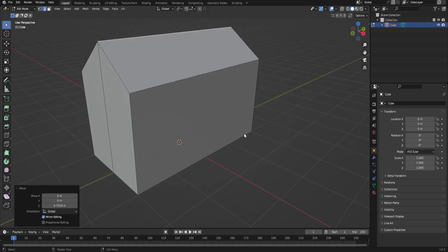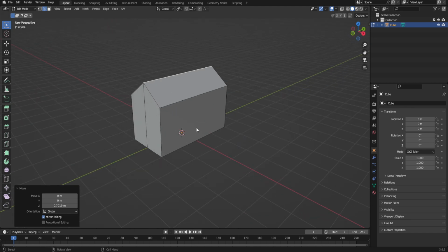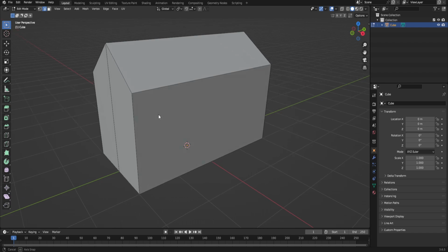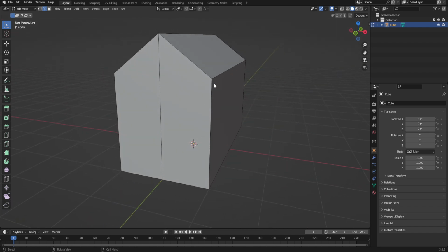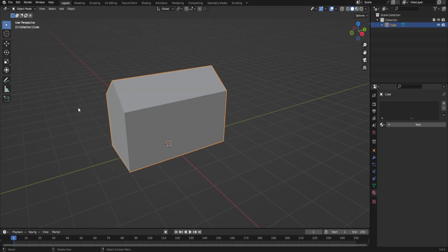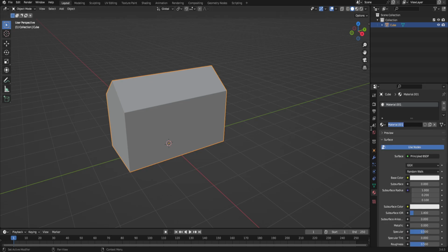All right, so now when you do this, remember this is not acceptable. This is demo quality. I want you to think about different details you can add to your piece that isn't just this. Okay, so first of all, let me show you how you can do multiple materials on a piece. I have a couple of textures that I grabbed really quick. One of them is siding, and I'll just type siding here. I like to name the materials what they are, because you're going to have to pull them up again, and it's good to rename them so it's not just new material 1, new material 2, etc.